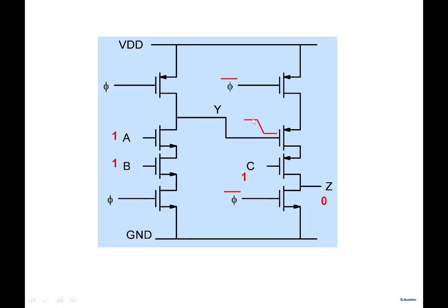So the incorrect part, which is 1, doesn't do anything to the PMOS. It doesn't turn the PMOS on. Remember, if 1 was the correct output, it would have remained at 1 and no problem. But the correct value is 0. So it takes time to go to 0, but then it doesn't do anything. When it goes to 0, PMOS is supposed to be on anyway. It should turn it on, and after a delay, it turns it on.